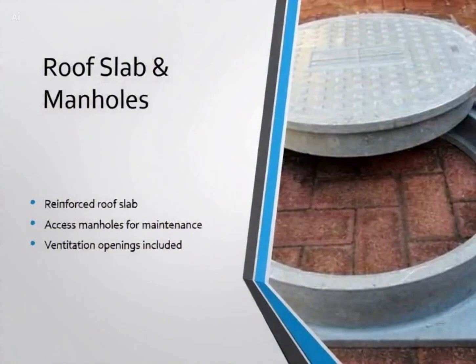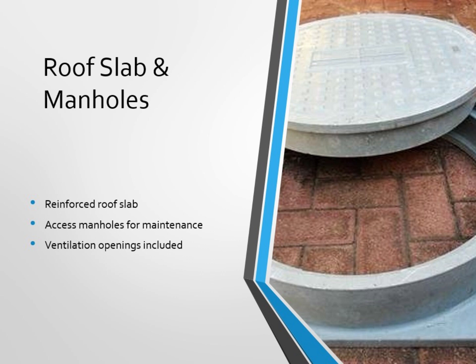The roof slab should also be reinforced. We will also include access manholes and ventilation pipe openings. The manholes are essential for inspection, pumping sludge, and general maintenance.